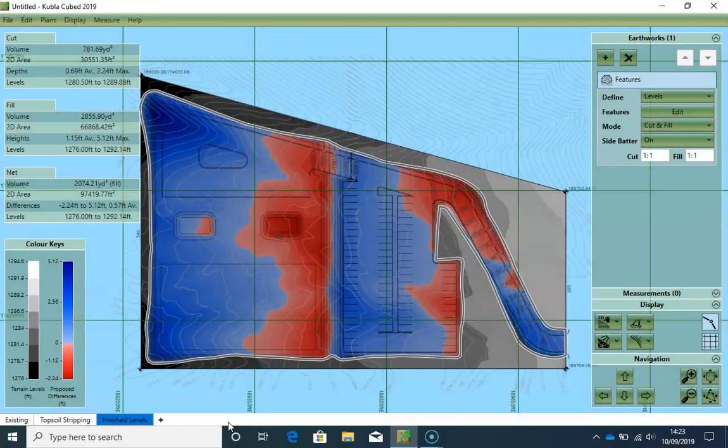Now the final step on most projects is to define paving depths. The drawing usually shows finished levels, and these need to be reduced to subgrade levels to get our earth volumes. There are a couple of ways to do this, but we are going to use the stripping method. This is when you use strip elements in the same phase to reduce the levels of the pavement thicknesses. So we have two construction depths in this project. Although they are not marked on these drawings, we will add a strip element and draw around the boundary of this area here.